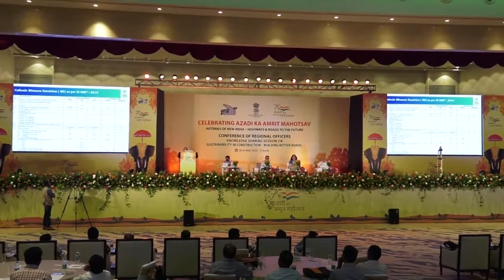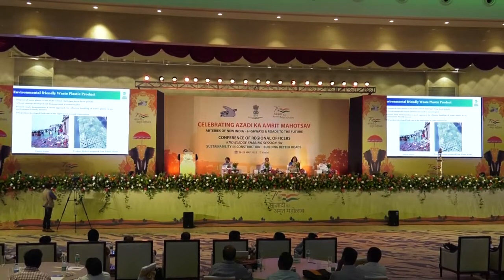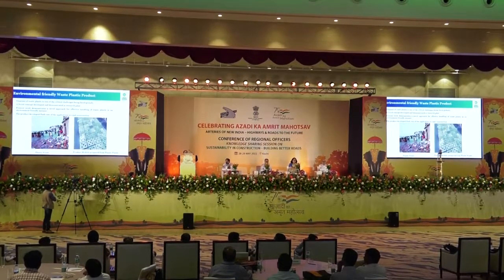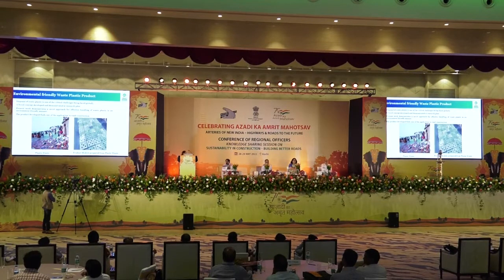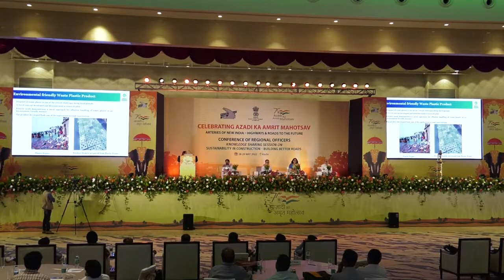Now coming to the last slide, which is BPCL, when we are talking about the waste plastic, and of course Dr. Anjan and Madam has already shared many things about waste plastic bitumen. So what we have done here, the specific thing is the blocks which you can see on the right hand side, these have been prepared by mixing the various mold. This is kind of a tray or the mold which we can say has been prepared by using waste plastic, and these holes we have created so that when we are putting bitumen or concrete in it, it can be directly laid in the road when we are preparing the base, and then bitumen can be laid over.